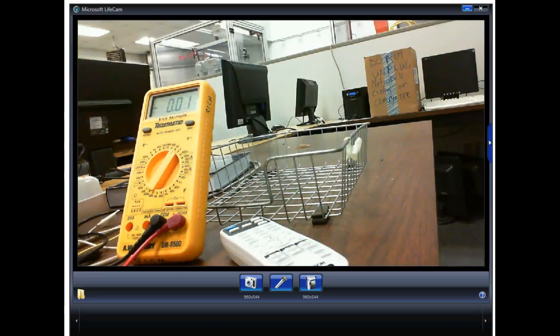So here's my collector. Here's my emitter. 5.86 volts. Yeah, because we didn't get the right base. Our base is a little low. If the base is a little low, the transistor's not turning on as much as we calculated. If the transistor's not cutting on as much, it's going to drop more voltage. So VE was lower than what we calculated too. But the sum of VE and this should still equal 10 volts, right?